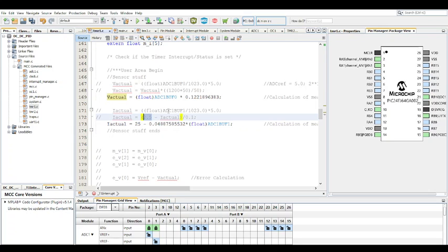Usually they're made to connect the other way, in terms of like you want to sense an AC current or something like that, where the readings you get are actually more than 2.5. And find out what the baseline value is. Sometimes it's not 2.5, it's like 2.45, 2.4 in fact, with a really weird sensor.